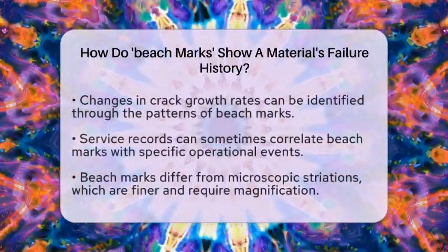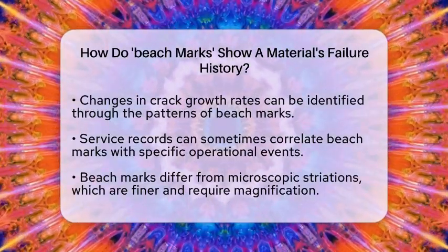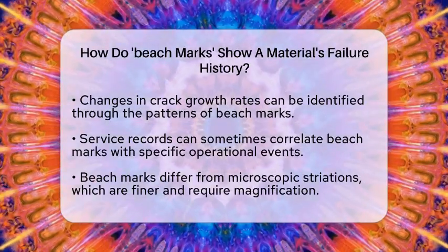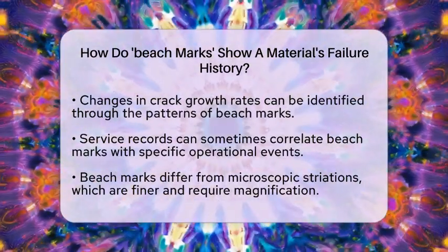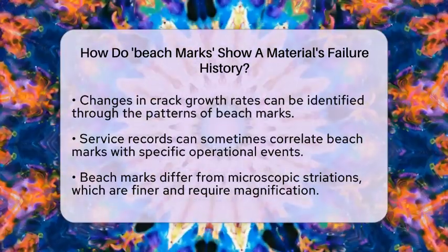In some cases, if there are service records available, the size and spacing of beach marks can be matched with specific events or operational cycles. This helps to reconstruct the timeline of the failure, providing a clearer picture of what happened.